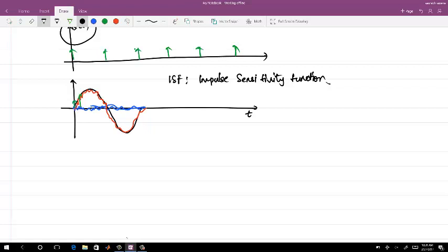On this periodic wave you find the output phase noise with respect to the input voltage. This includes all the kinds of frequency translation which will be happening, because it's a periodic system in the end. And then you find the total phase noise. What I have just talked about is about one location. The actual phase noise at the output is dependent on all the locations.